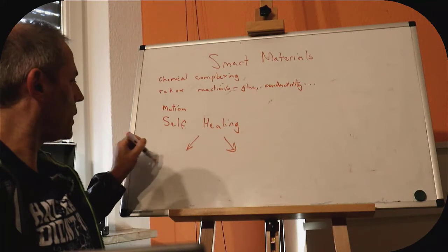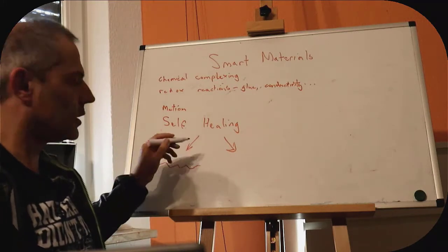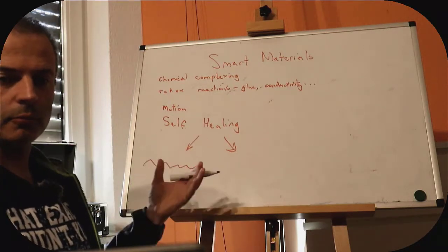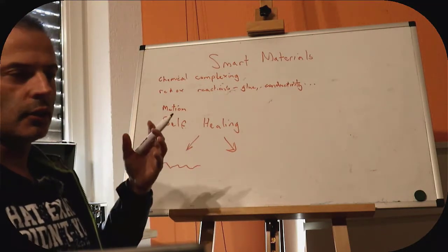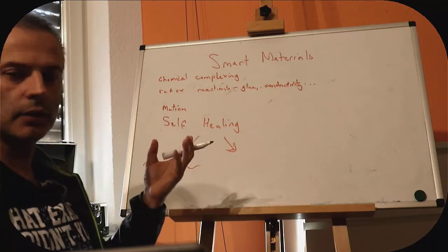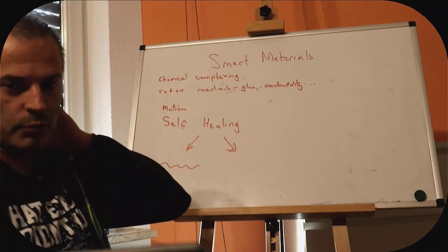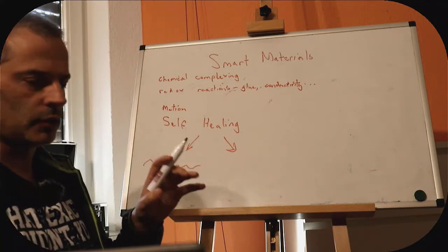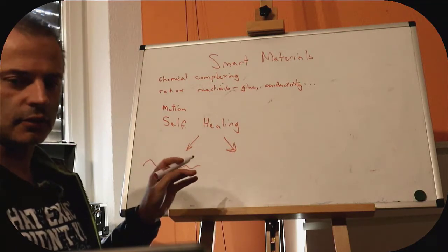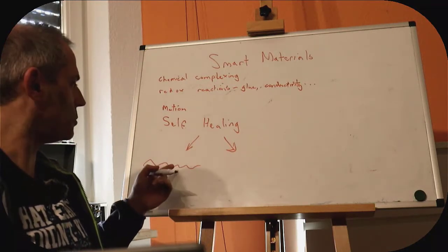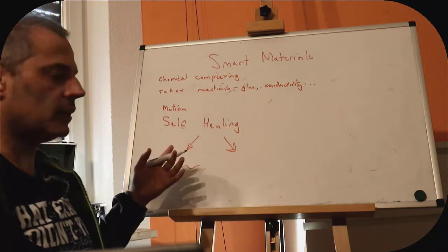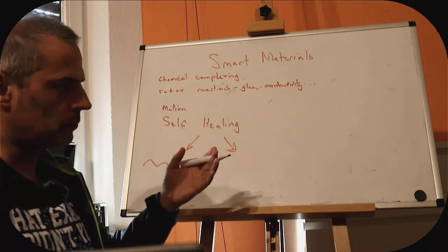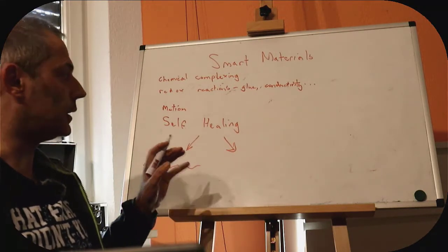So typically, if we have a polymer, for example, we have a carbon chain, and this is held together by connections between carbon atoms. If we have a metal, we have metallic bonds between metal atoms. If we break these, or even move them around, it is difficult, though not always the case. There are a few special cases. It is difficult to reform. So if we break our chain physically, then it is not going to go back to where it was. If we move the chains around, then very often we can get it to go back to where it was.